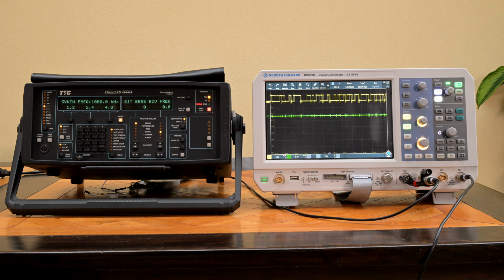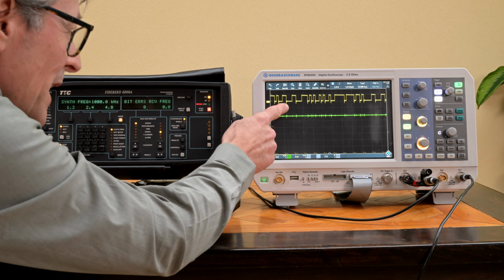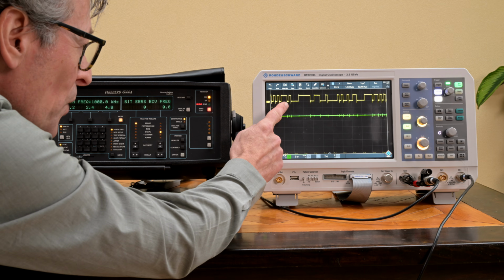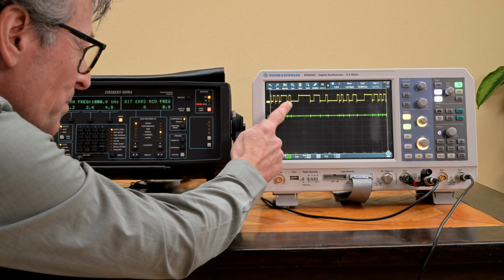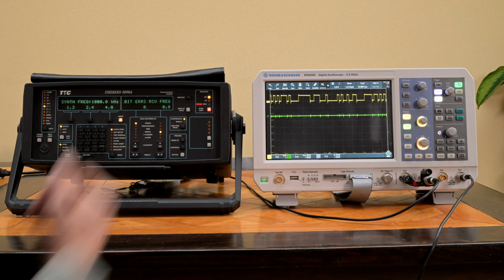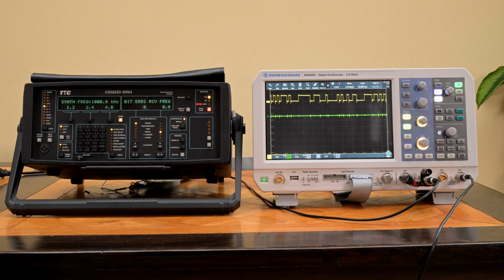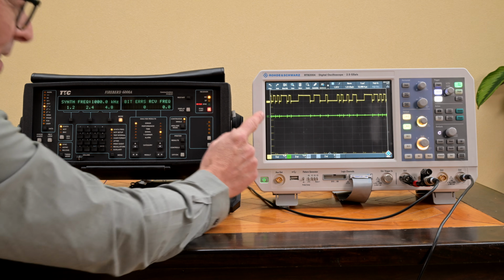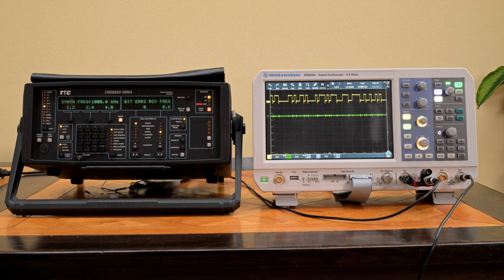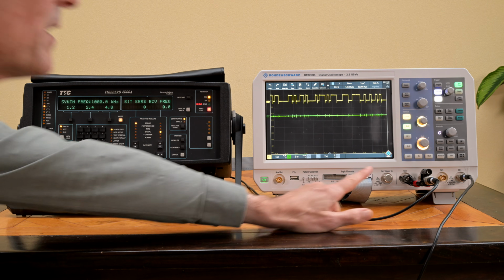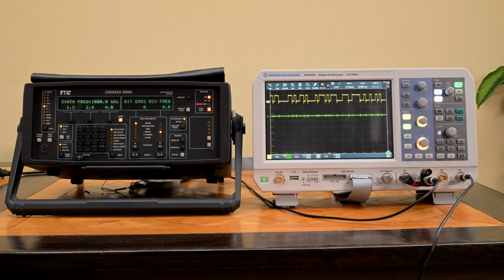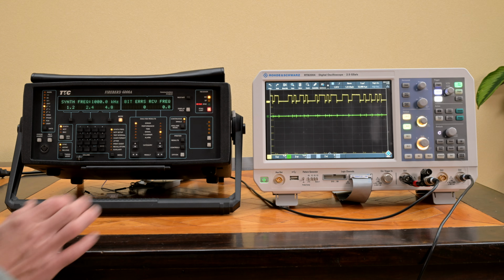So this is the regular type of output that you would get from here. I'm syncing it here a couple of times, and the center pin basically has a 5-volt TTL-like signal, and the shielding has basically nothing right now in this setting. And also note that I have a reasonable amount, or unreasonable amount, of ringing. I deliberately did not put a termination resistance of 50 ohms there, so we could see any such signals.